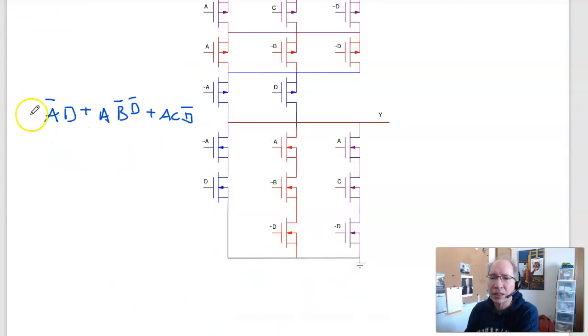That's the logic down here. That's Y bar. The reason I like doing Y bar circled with zeros is because that gives you the logic down here. When these are true, Y is pulled low through like 0.01 ohm. So that's the Y bar. It's pulled low.